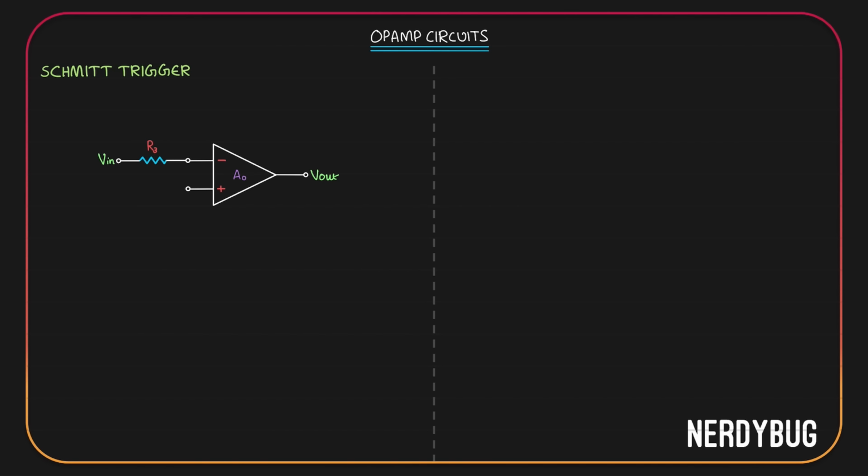Till now, we have only seen negative feedback, the kind that stabilizes the Opamp, reduces the gain, and makes circuits like buffers and amplifiers. Negative feedback tries to cancel the changes in the output. When output rises, it brings it down. Schmitt trigger is basically a comparator. We want the output to be always saturated. Instead of a negative feedback, we will use a positive feedback.